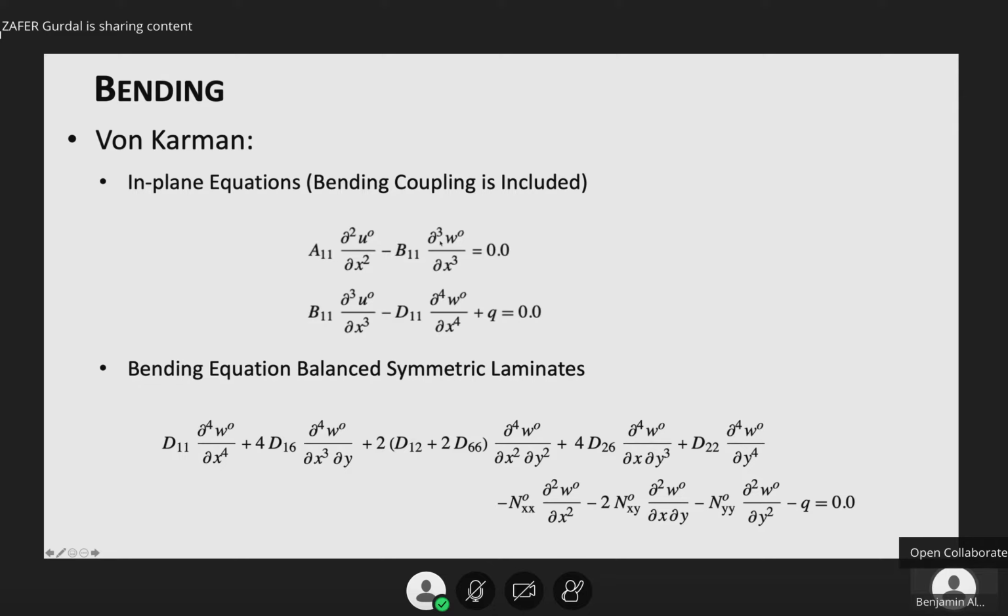And then there is the bending part coupled here. This is actually for the coupled cylindrical bending case. I just want to show you that the W expressions are here. If you look at just the bending expression, the simplest form that we can deal with is still nonlinear in terms of these Nx, Ny, Nxy's that multiply the W displacement terms, out-of-plane displacement terms.